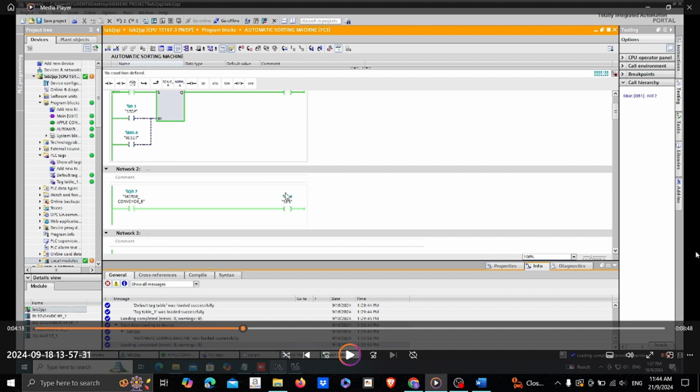The system includes an additional sensor SE5, which is positioned to detect any box that is present at a critical location in the sorting area. If sensor SE5 detects a box, the system responds by stopping conveyor box B. The conveyor must stop immediately to prevent box overflow or collision, ensuring that the boxes are sorted and moved one at a time.